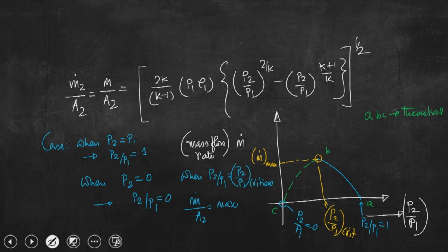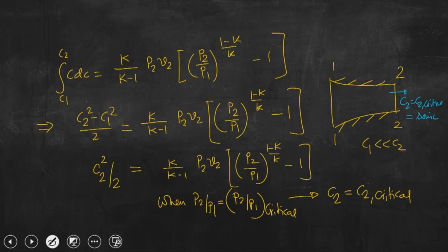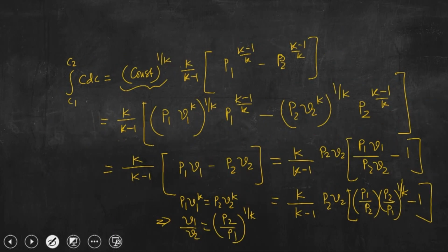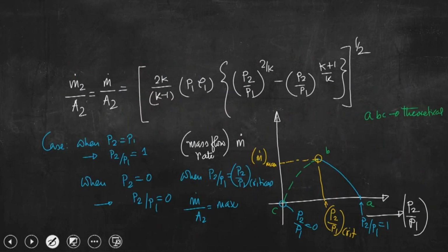through the medium itself. But since the nozzle exit velocity is the sonic velocity, which we established a few minutes back, that information about further reduction in pressure will not reach the inlet section of the nozzle to increase the flow rate, and as a result the mass flow rate will remain constant. This is the experimentally measured data. So, this is A, B, and I am writing D. This A B D is the experimental curve.